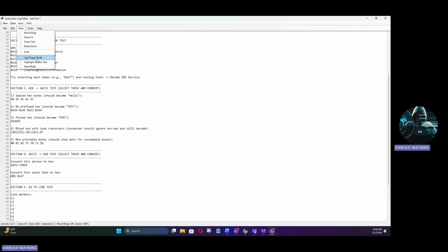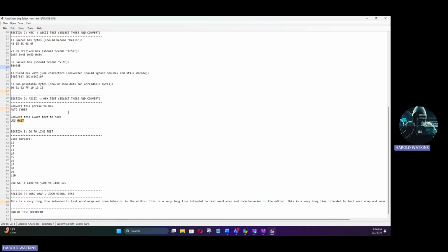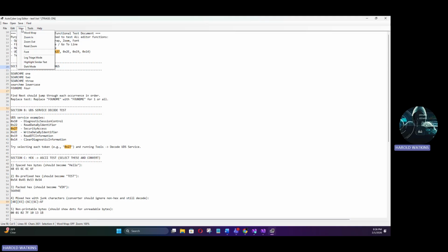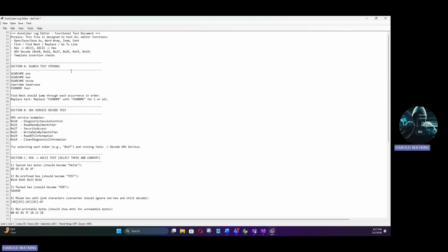So for this example, I have service 27, or mode 27, set up. What this will do is filter for all your security access issues, which you see here. And then we release it by just clicking on it again. But this could be set up for any issues in your industry or in your field to filter directly for, so you don't have to filter through and read through everything.